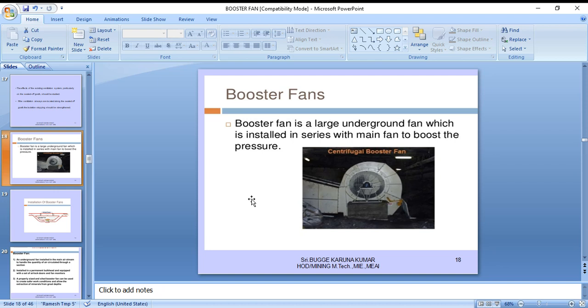There are three ways in which the desired quantity of air may be distributed to the branches of a parallel circuit having unequal pressure drop across the branches. Controlling splitting using regulators in the low resistance splits to balance the circuit. Controlling splitting using booster fans in high resistance splits to create a balance. Free splitting, achieved by decreasing the number of airways, balancing pressure drops on the basis of economical operating costs. They are listed in order of increase in performance.